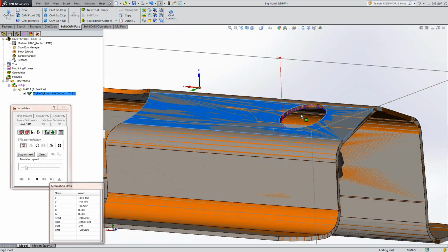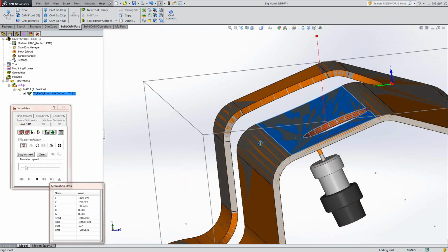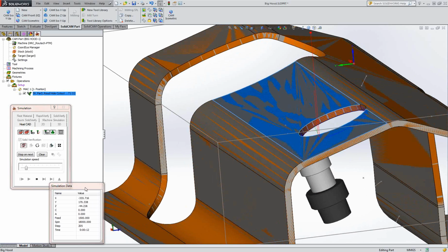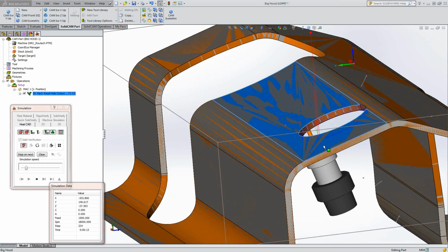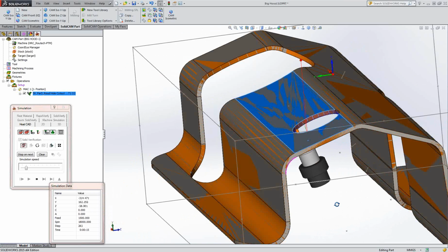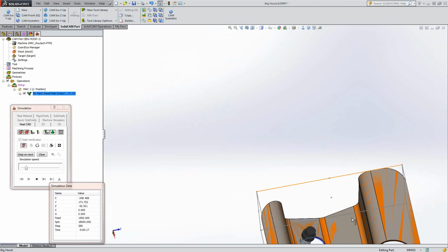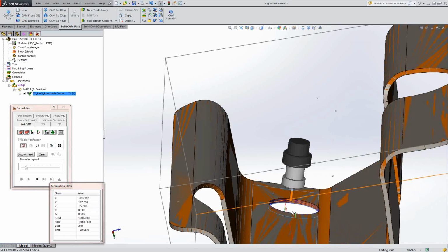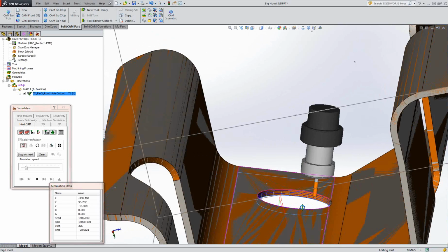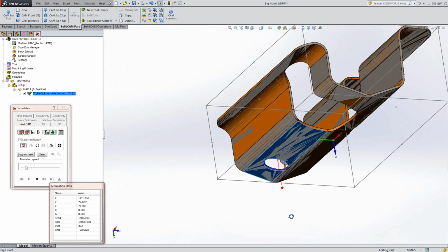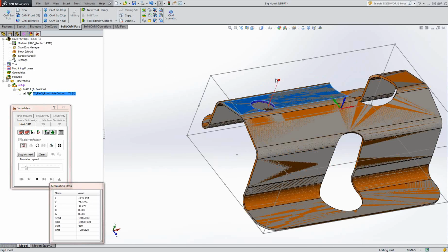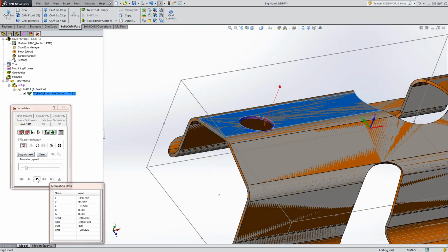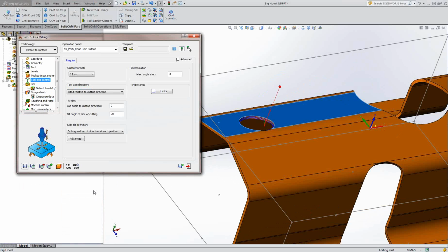Because there are so many connotations here and you may wish to do so many different things with it, it's up to yourself to check that that is in the right orientation. Now that's a perfectly legal toolpath if it's in this orientation. It would, however, crash through whichever way you did it because it's trying to get to this side. So that illustrates how you can easily go wrong, but it's just as easily fixed.